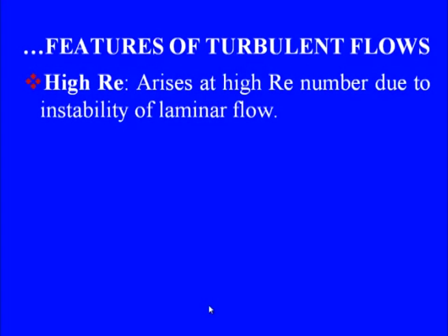Now, as noted earlier, turbulent flows always occur at high Reynolds number due to instability of the laminar flow, and please remember this: though the turbulent flow is random, we talked about various length scales of widely differing magnitude. We talked about some very large length scales which are linked to the largest eddies, and very small length scales where the energy is dissipated due to molecular action.